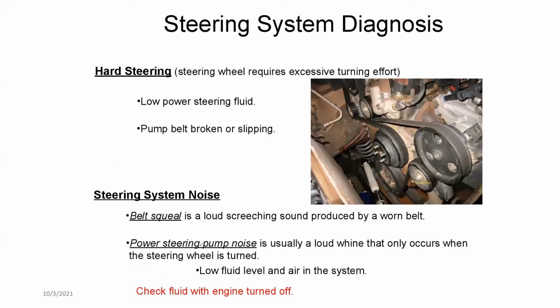And if there's hard steering, if it is a power steered vehicle and it is very hard to steer, the usual causes are low power steering fluid, or the pump belt broken or slipping, right? But belt slipping usually comes with a squealing noise, though not all the time. It's not all the time. So for maintenance, there's a rule of thumb or something like that.